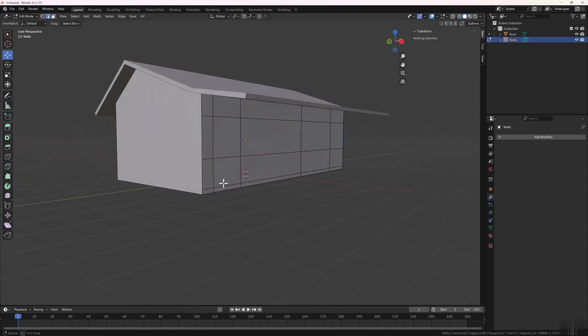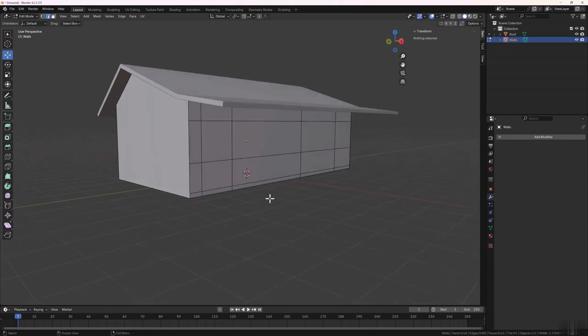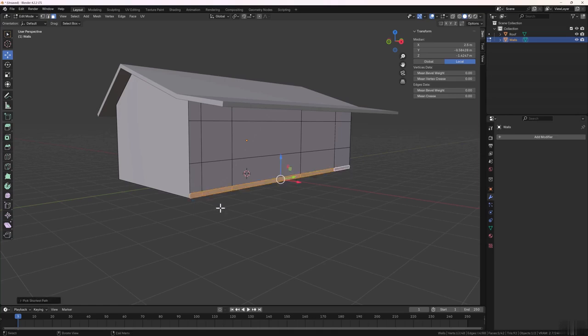So now let's go ahead and create our stoop on our property. Let's press 3 on the keyboard so we can select faces. It's changed to faces just there. Now I could actually just hold shift and move along selecting these, but it's not too bad here. We've only got a few faces. But let me show you an easy way of doing this for future. So I'll select that first edge. Now I'll hold down Control, go along to the last edge that I want to select, grab that, and it'll select obviously the first edge and the last edge, but all the other edges in between.